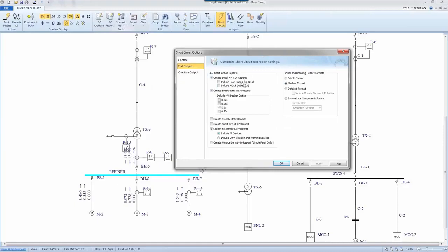We have gone to every IEC MCCB reference standard to see how IEC classifies different molded case circuit breakers and defines different test X over R for them based on their interrupting capability. And we have included them in our reports. You would see them extremely useful when you go to those reports.